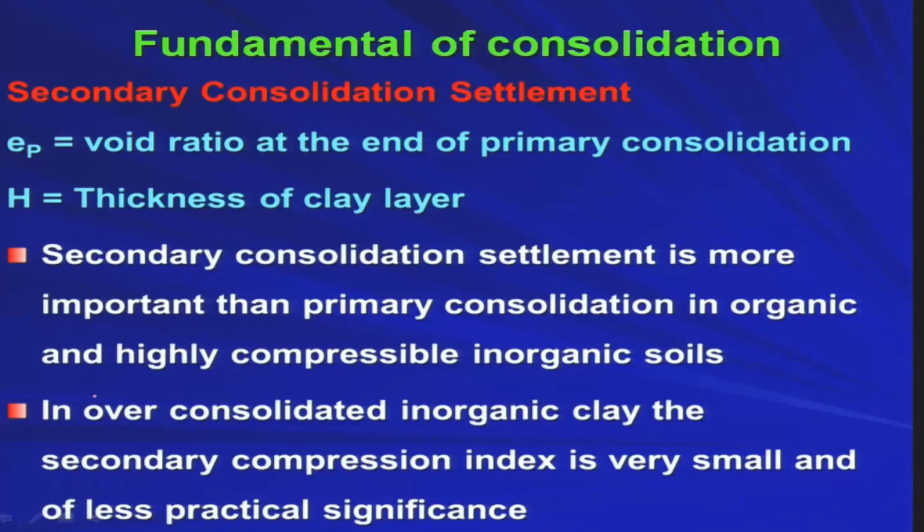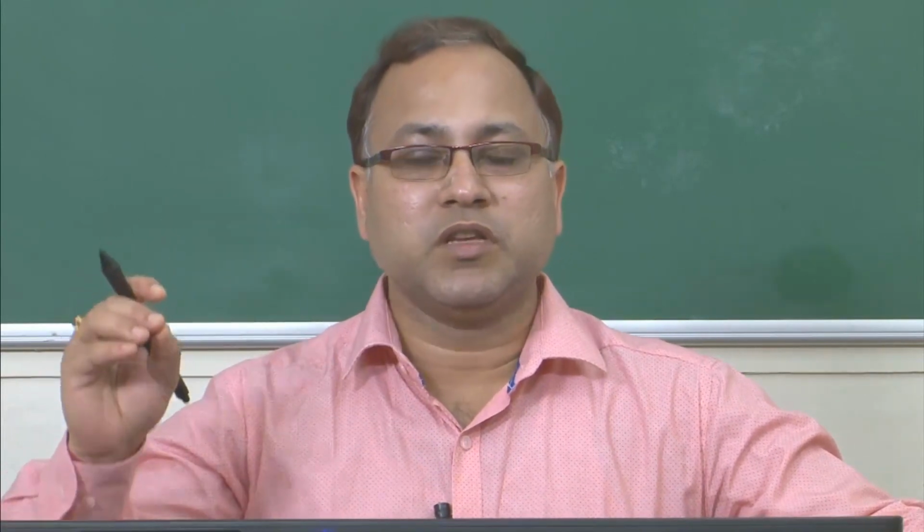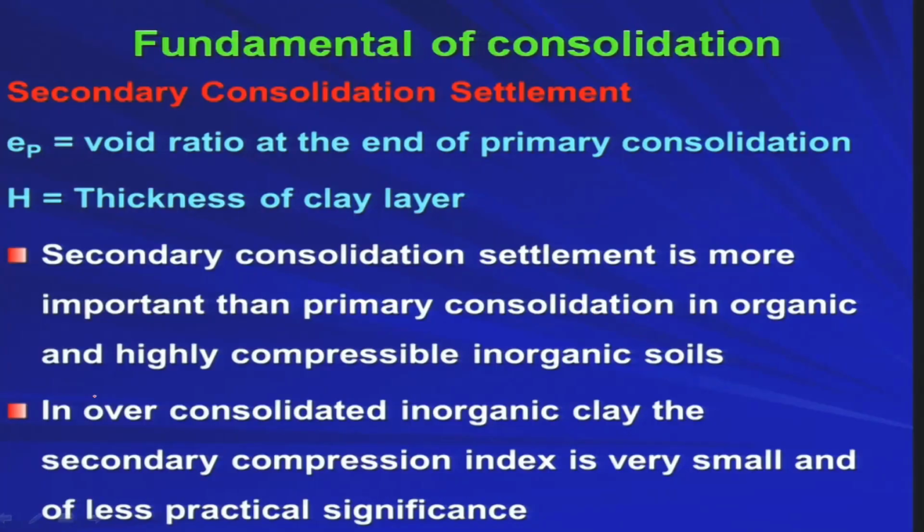So, secondary consolidation settlement is more important than primary consolidation in organic and highly compressible inorganic soils. Please try to remember this. It will give you a significant value in case of organic as well as highly compressible inorganic soil. The soil which is highly compressible, that means even after the primary consolidation you will observe a significant amount of secondary consolidation. However, in most cases in over consolidated inorganic clay, the secondary compression index is very small and of less practical significance.